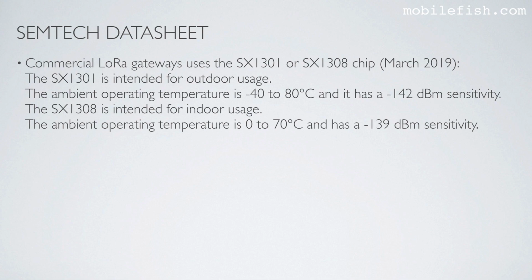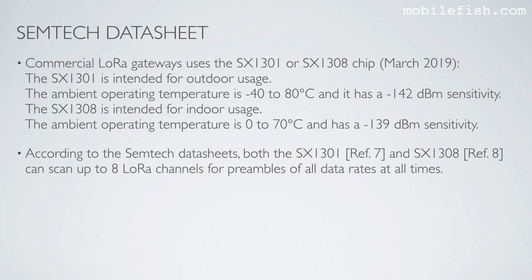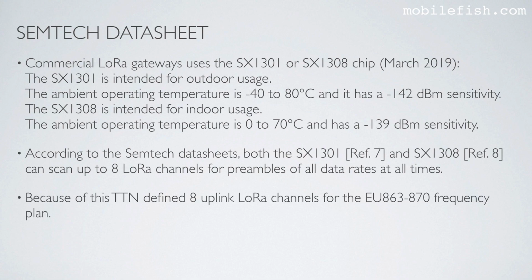The ambient operating temperature is 0 to 70 degrees Celsius and it has a -139 dBm sensitivity. According to the Semtech datasheets, both the SX1301 and SX1308 can scan up to 8 LoRa channels for preambles of all data rates at all times. Because of this, The Things Network defined 8 uplink LoRa channels for the AU 863 to 870 frequency plan.